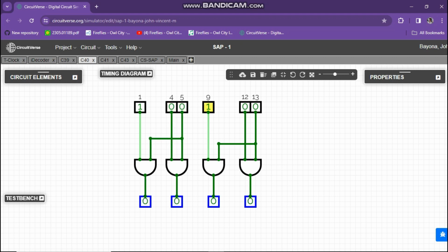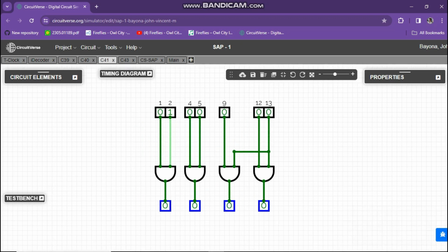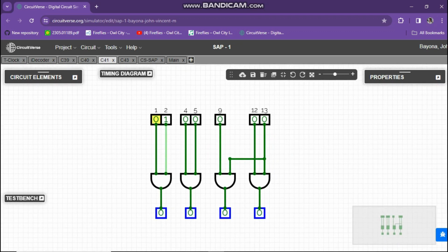The B register could be one of these general-purpose registers and it will be used for various purposes such as storing data temporarily during arithmetic or logic operations. During an addition or subtraction operation, data from the memory is loaded into the B register and the result is stored in the accumulator.